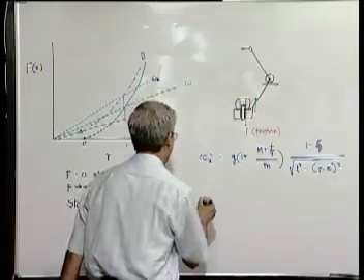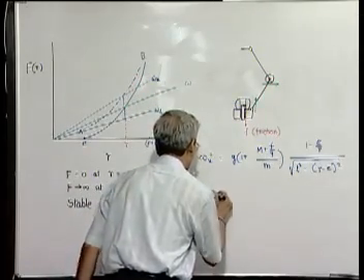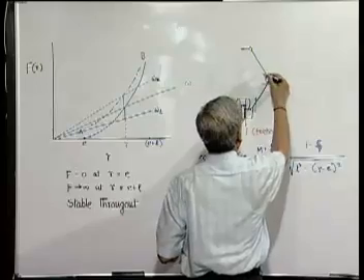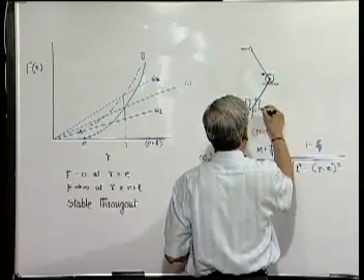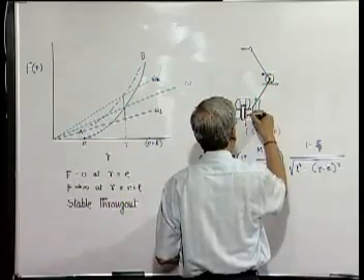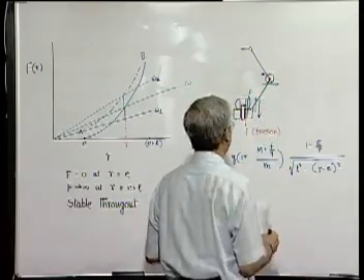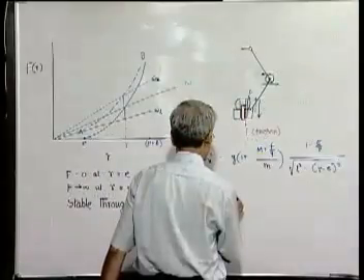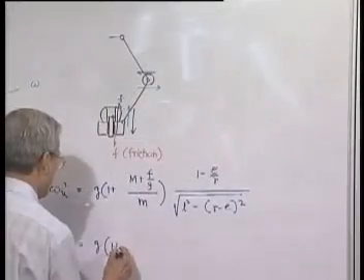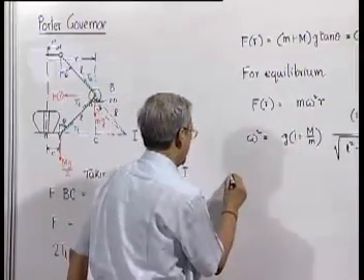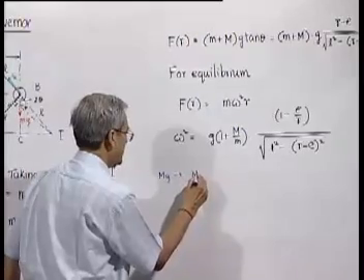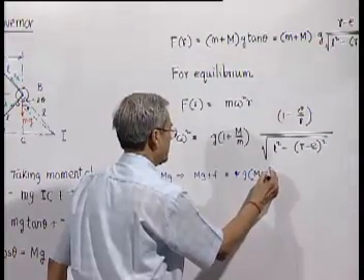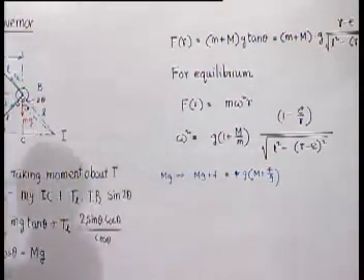will be this, and when we try to find out the lower speed limit, that means the speed is decreasing in this direction. When speed is decreasing, this tends to move in this direction, and obviously then friction force acts in this direction. That is, now it opposes the weight, so it will be mg minus f. So this lower limit can be found out from the same expression, only when mg is replaced by mg minus f. Then what is it going to be? G into m minus f by g. So m will be replaced by m minus f by g.